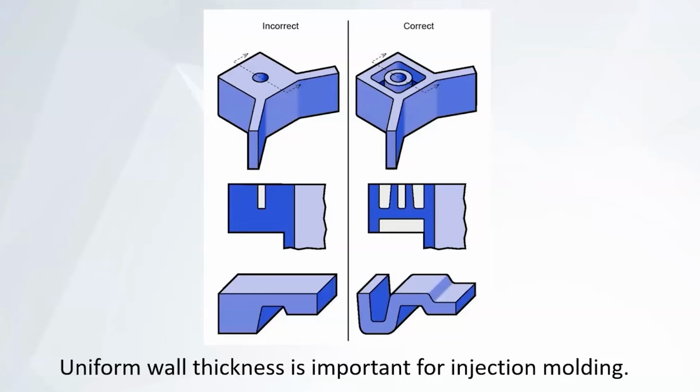During this cooling process, these thin walls will cool quicker than this huge thick block. And what that does is that creates a temperature differential between the thick parts and the thin parts. And that temperature differential causes the part to warp as it cools. That's the main reason you don't want to have thick areas and thin areas.